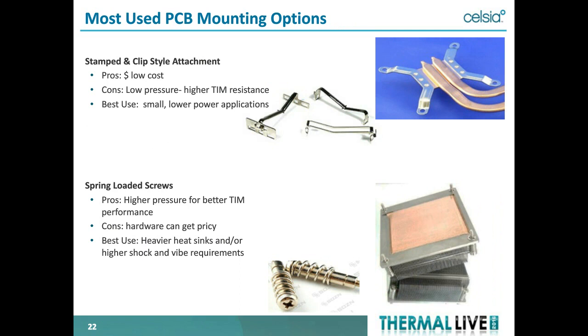We're going to jump into mounting options, and we're going to go through this quickly because the mounting options for heat pipes and vapor chambers are the same as any other heatsink. We just showed you some examples here. The upper right-hand corner is a notebook application where they're simply soldering the two heat pipes to a stamped-out spring clip that probably uses push pins or screws to hold it down onto the board and onto the device. Once you get up into higher end applications, higher power servers and things like that, you move up to the typical screws and springs.